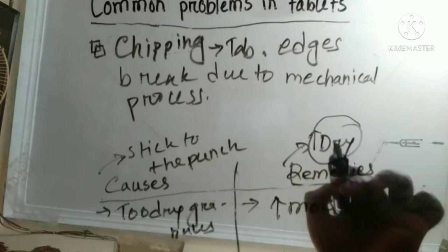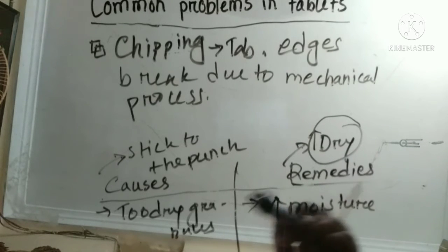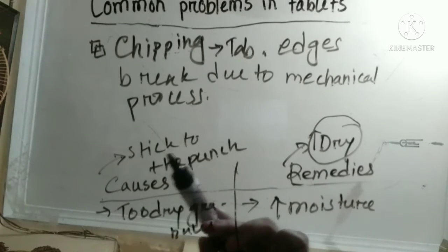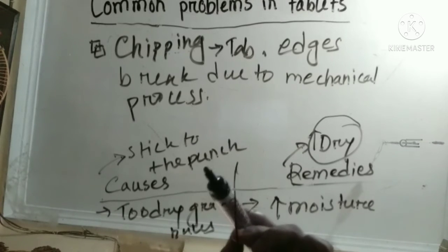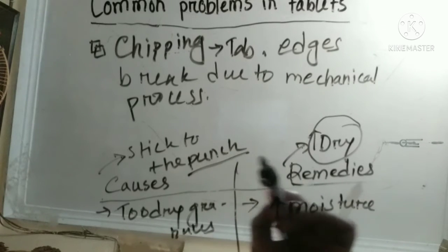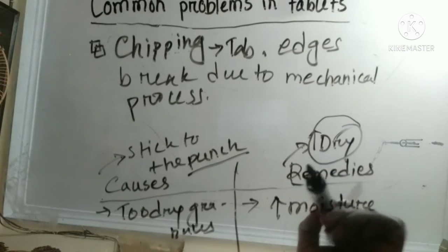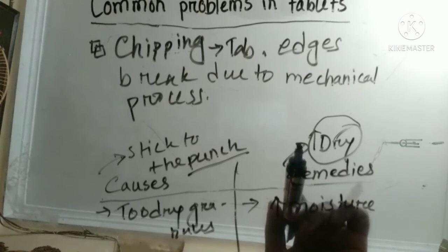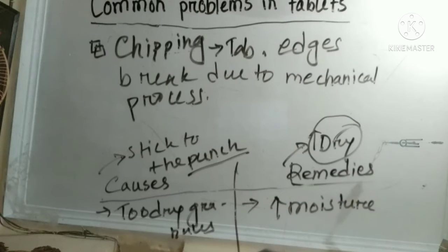Granules properly. Okay, we have to dry the granules properly. In case when granules are sticking to the punch, we have to dry them properly. So our next cause is